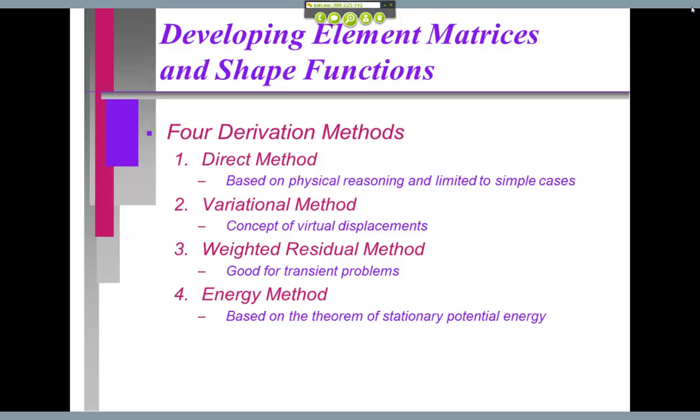They're just blasting out elements, and the elements are usually pretty crude, pretty rough as far as their edge length. But as they get closer into the detailed design phase or to the final production phase, you will see them ratchet up the node count, the element count, and begin switching to higher order elements at the same time to get better accuracy.